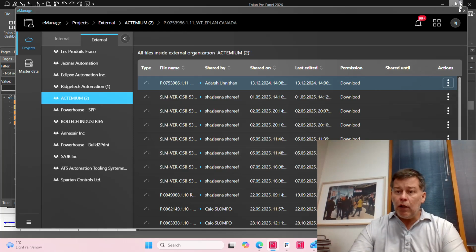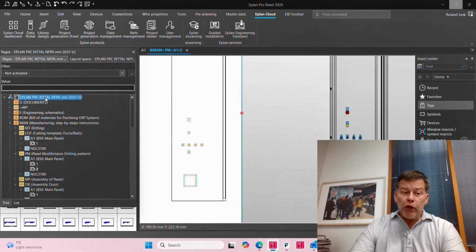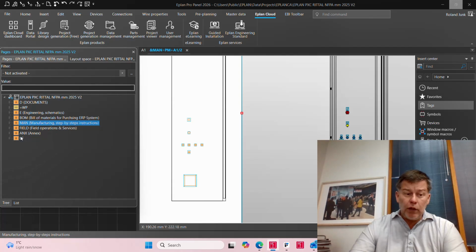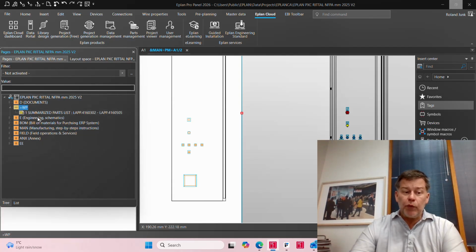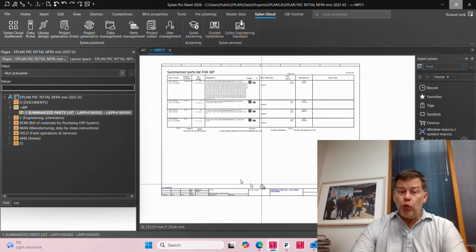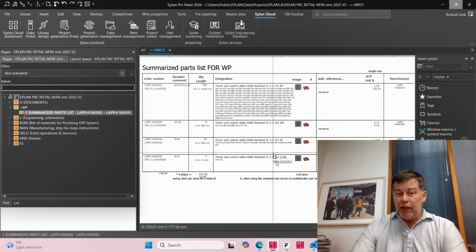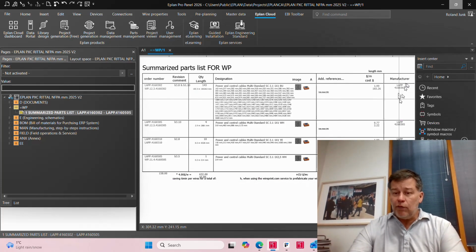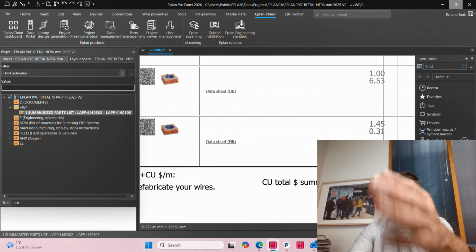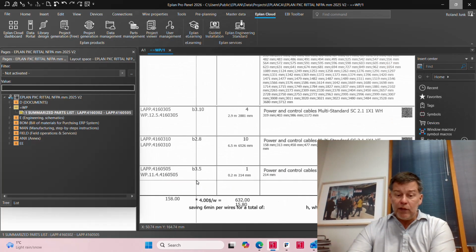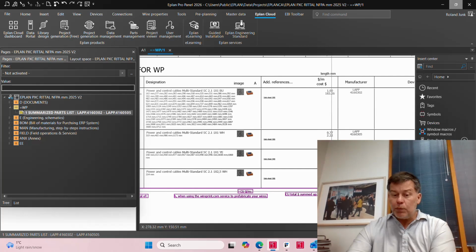I can then, of course, in my case, look at the different routings. I will often even generate a specific file that will tell me, okay, these are the wires that you routed, and we have them on the machine, on the EPLAN WT, and I can tell you right away we have that much in value for all your copper and wires, because I calculate based on the length that is required and the cost per meter.